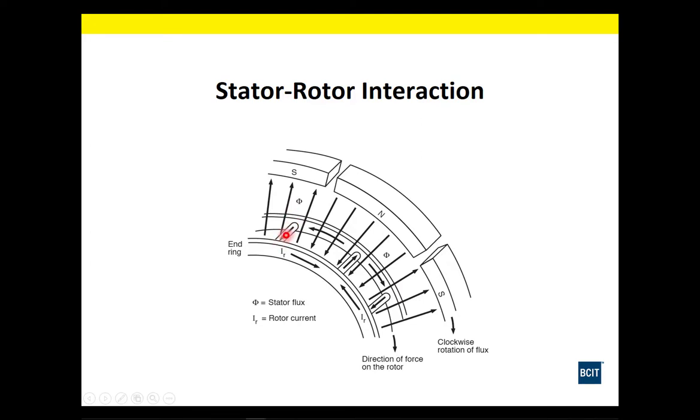to establish what current direction is going to be through this rotor bar also, but our lines are going to be going upwards instead. So just a matter of pointing the flux up, and the thumb's still going to be going over in the same direction, but our current now is going to be coming towards us if you use your left-hand rule. Now let's see which direction our rotor is going to be moving.